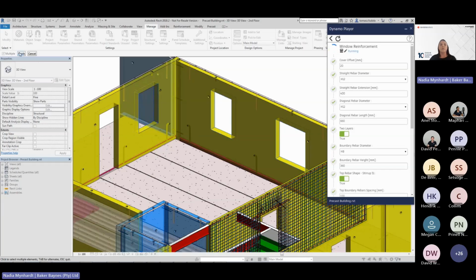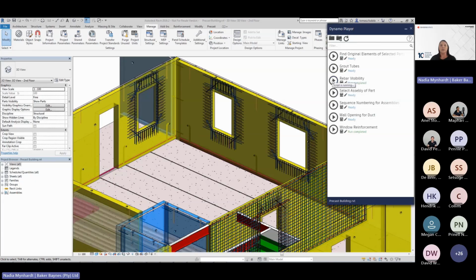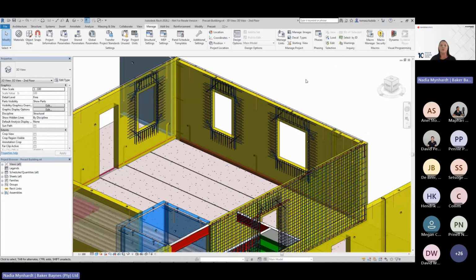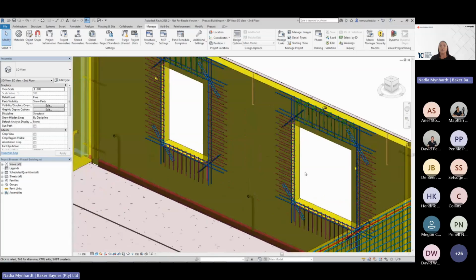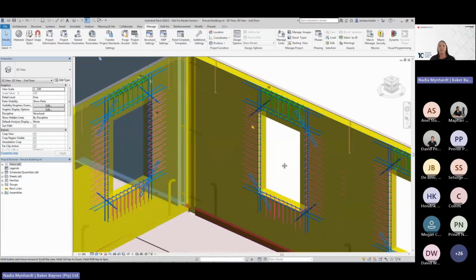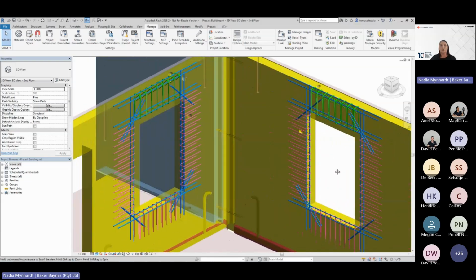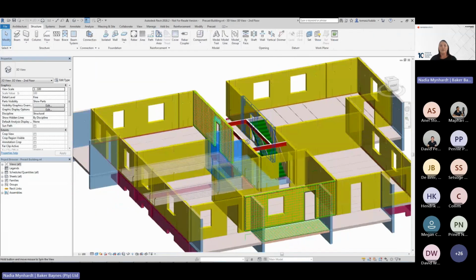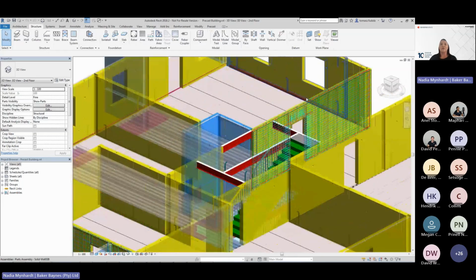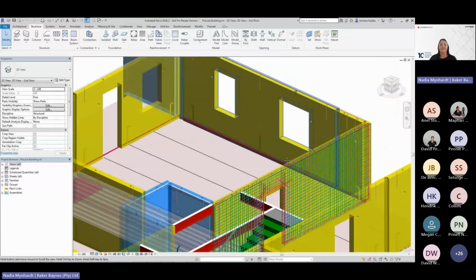It's just a simple example, but you could have in your own script said, I want rebar in this pier. And you will be asked, do you want it to be at a certain spacing? Let's say you want 200 mil spacing, you want Y12s, top and bottom. You can say you want Y16s at the top or Y12s at the bottom. You can think of it. All you do is specify that information. You go select the object you want rebar for, and it will instantly create the rebar for you in that object. So you can produce those drawings within the next hour and impress your boss because everything is going to be okay.